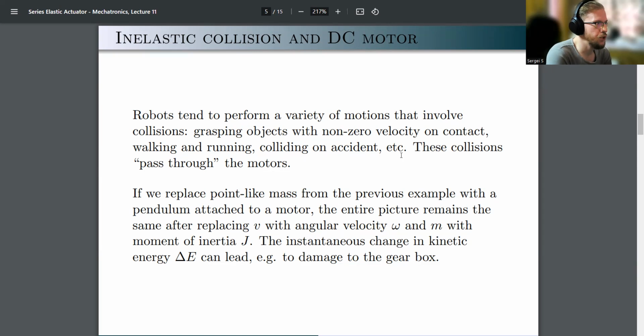For example, you can teach them what they need to do. Imagine a cobot that needs to grasp, pick and place. You can teach them by demonstration: physically move the robot's grip towards the object, make it pick, then move it to the next place, make it place, and say, okay, this is good, repeat. It would be much faster than trying to program them.